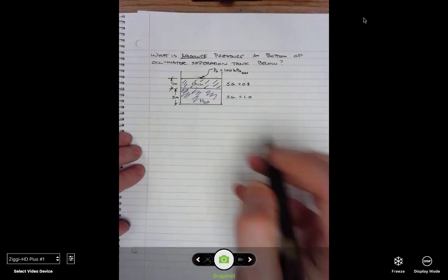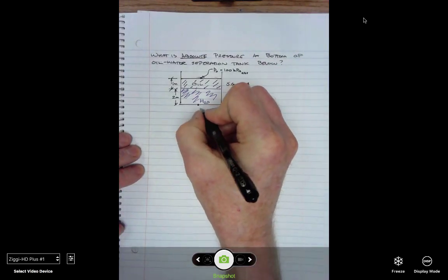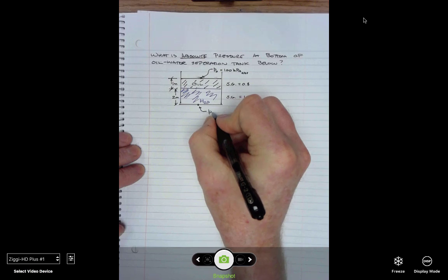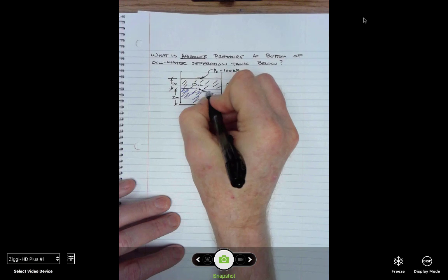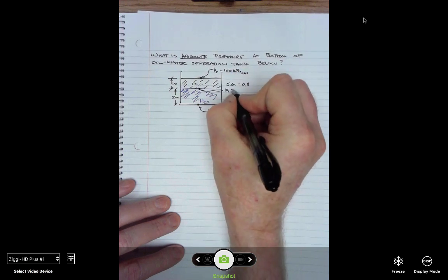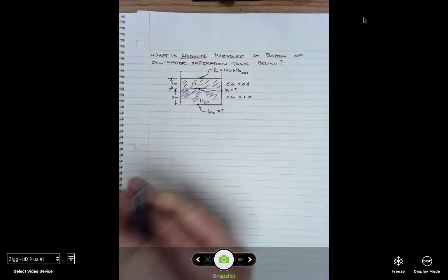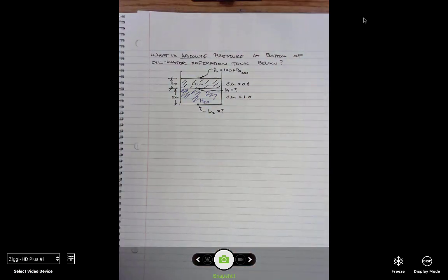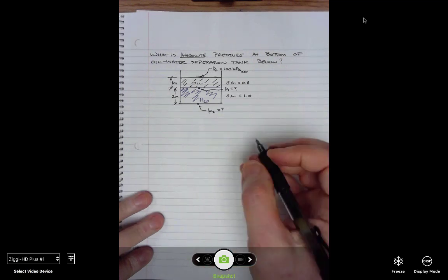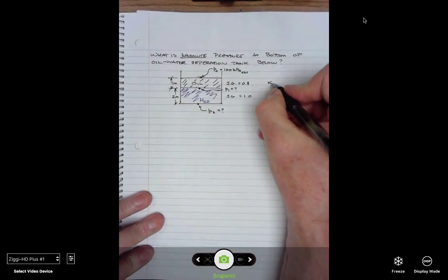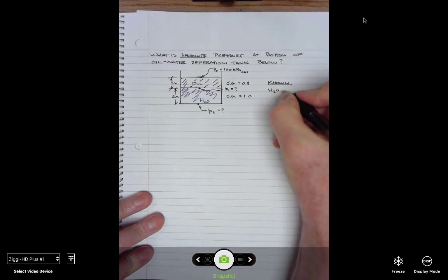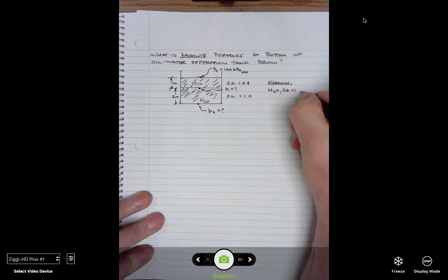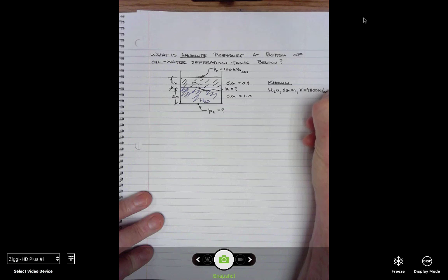And we want to know what the pressure down here is. We'll call that P2. I'm going to introduce an intermediate pressure, P1. We're going to need it, if not directly calculated, it's going to be incorporated into our algebra, so we might as well include it. So let's list our knowns. Water, specific gravity equals 1. Gamma is 9,800 newtons per meter cubed.